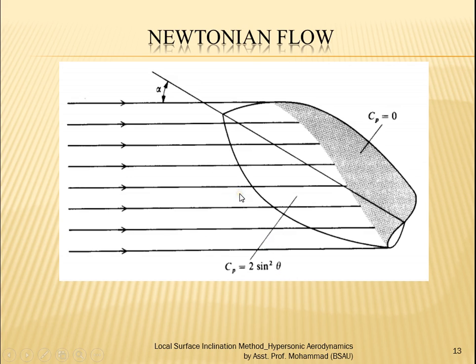Now one more thing that is being made clear here is when we have to find what is going to be the total pressure rise, the total lift on this body when the hypersonic flow attacks it. The angle of attack is available here, but this will not have the same deflection everywhere, because the angle of attack may be like this, but this will affect locally. We'll have this theta, the deflection is actually a local deflection, and this will vary throughout the body.